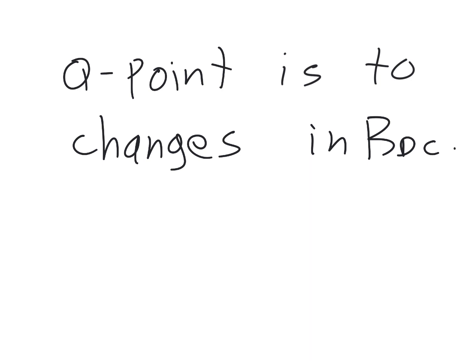When you're looking at a linear AC amplifier, big changes in beta can pose serious problems. What we don't want is a very unstable Q point, which causes the signal to distort and clip. That's not what you want.